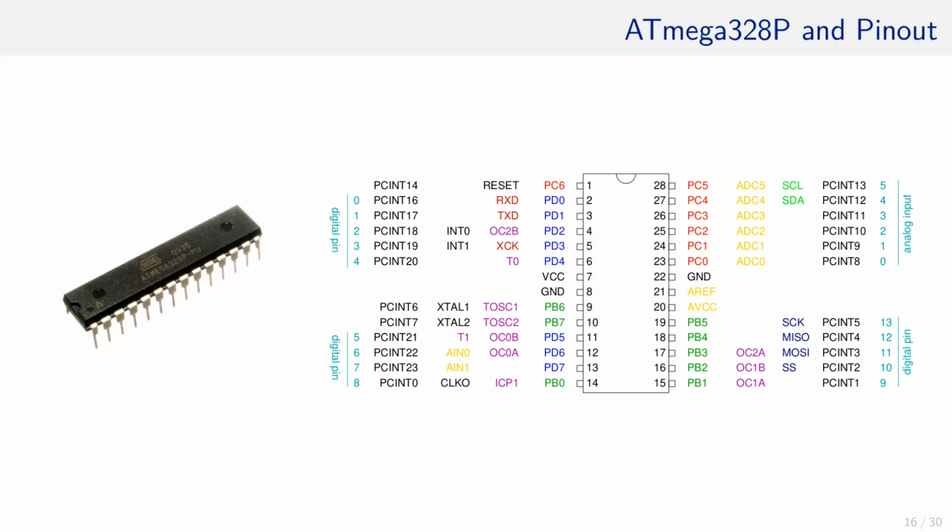For instance, in many scenarios, a sensor is read using the I2C or TWI interface here, and the resulting data is to be stored or transmitted using the UART or SPI interface. That is not a problem, since the pins for both transmission protocols are mutually exclusive and there is no overlap. That means the sensor can be read and the data transmitted at the same time.